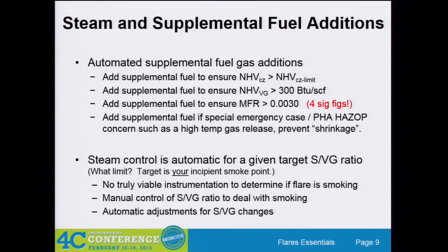Well, if it's a cold day, you could have thermal contraction of those gases in your header. They're contracting faster than you're adding purge gas. Suddenly you're creating a low pressure, and you could suck oxygen down the tip, suddenly creating a combustible atmosphere. Then it gets up to your pilots, and boom, you've just ignited your flare stack.